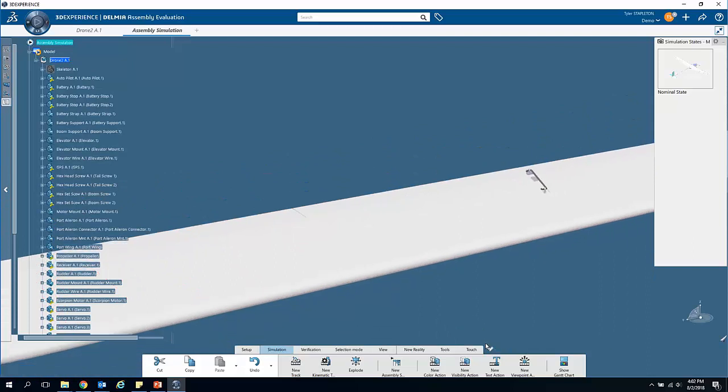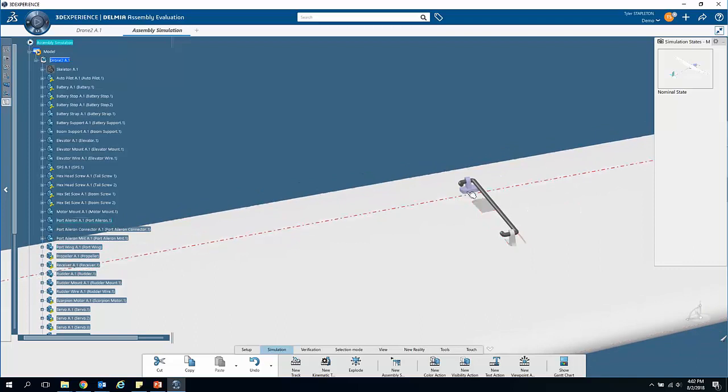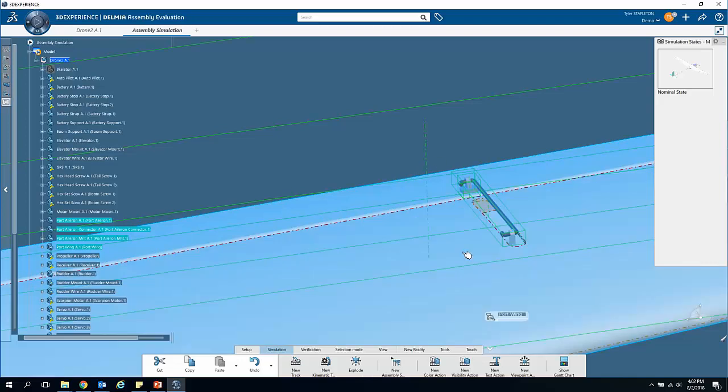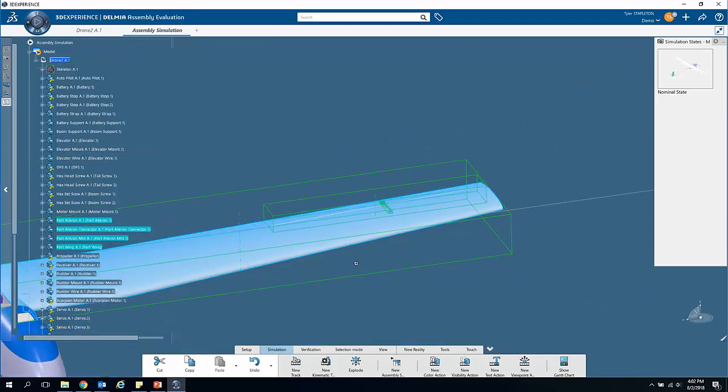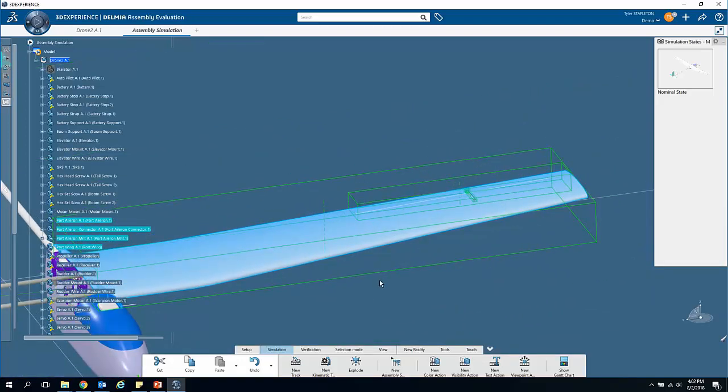So what I'm going to do is hold down my control key and select individual parts that I want to move. Good practice is to start with the smallest part and work my way up. Right click. So I'm holding down control, that's left click on that, and then that control arm, the control surface, and the wing. And now I've selected that whole sub-assembly there.